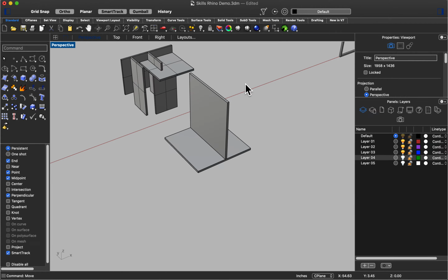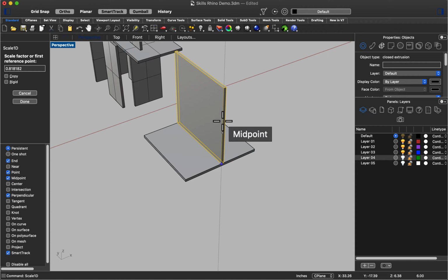So I click the end, and then I click the end of that line as well. So I click the base point, and then I go up, and now it's asking how tall do you want that line to be. I can type in a dimension, or I can click anywhere I want. But I know that that plane is 8 inches tall in my cube, so I'm going to type in 8 and then hit enter. And now it's made that plane smaller.